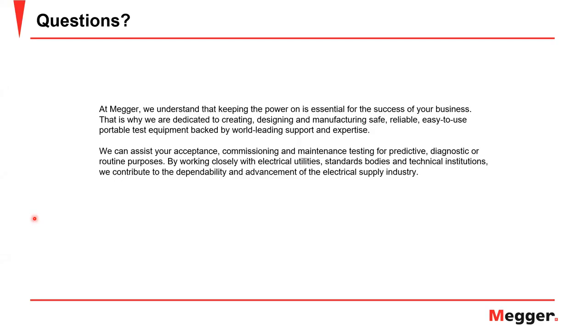So there is this manpower cost and the outage cost. Whereas a fuse saving scheme will be good because it will also increase the reliability in indices like SAIDI and SAIFI, but it will decrease the momentary indices, because there would be a lot of momentary issues that would happen.